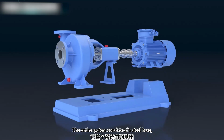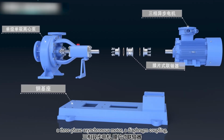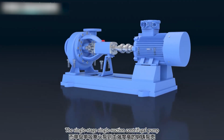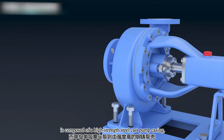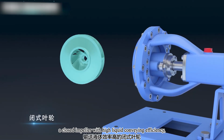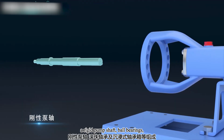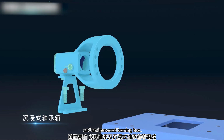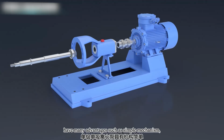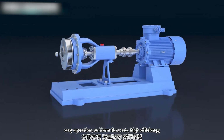The entire system consists of a steel base, a three-phase asynchronous motor, a diaphragm coupling, and a single-stage, single-suction centrifugal pump. The single-stage, single-suction centrifugal pump is composed of a high-strength steel cast pump casing, a closed impeller with high liquid conveying efficiency, a mechanical seal to prevent medium leakage, a rigid pump shaft, ball bearings, and an immersed bearing box.